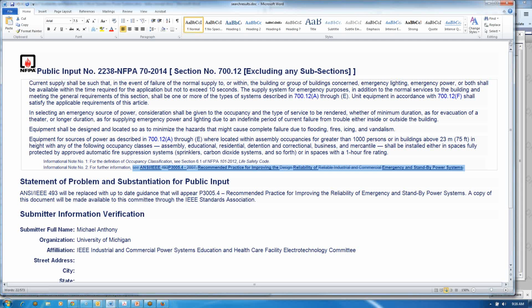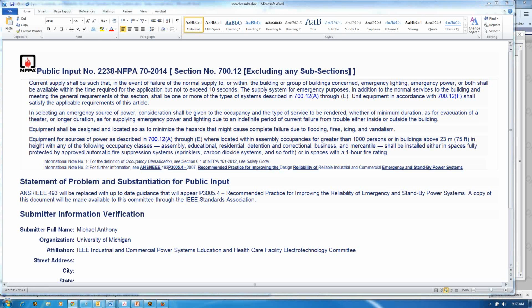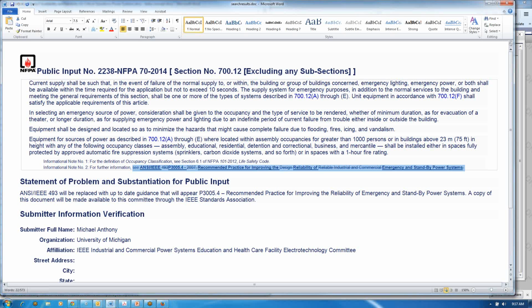So unreliability is 1 minus the reliability. Unavailability is 1 minus the availability. And as I was saying about having objective analyses, suppose you want to consider putting in a second utility feed, and you should then say, okay, well, what is the reliability I have now, or availability? We probably want to get the definitions of those two concepts established in the standard under discussion here.